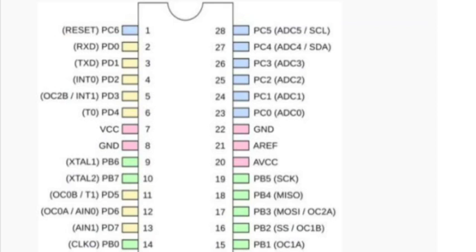If you look in the lower right-hand corner, you're going to hate that the SPI pins are shared with 2 of the PWM pins. And, yeah, that's always a choice you have to make.